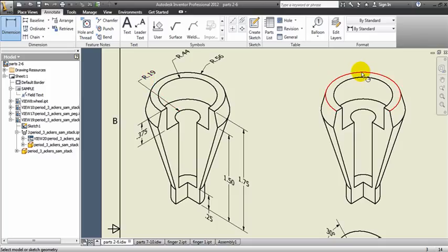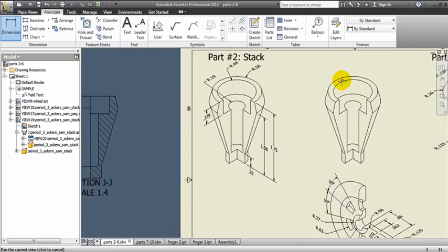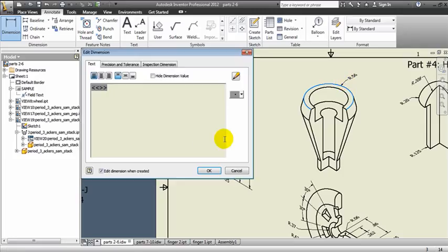So first of all, if I'm going to dimension this circle right here, I don't want to lock on green, so don't ever have a green dot show up, otherwise this thing doesn't usually work. So click somewhere else besides where it's green, and then I got my radius is 0.56.